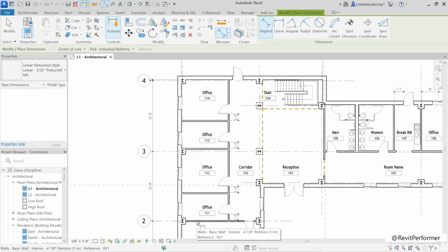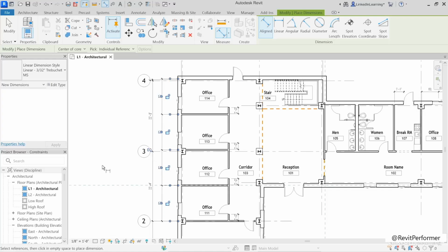And this wall down here, the center of core is where the studs are. This one, this one, this one. So all the studs are the same in those 4 walls because they're right in the center. But notice that the studs on the exterior wall are offset, right? So this is how I'm going to ensure that all of those offices are equally spaced. I'll come outside the plan, click to place the dimension, toggle the equality, and just like that, you'll see that we now have all 4 of those offices equally spaced.